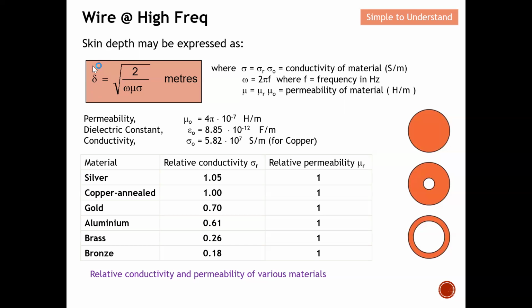Okay, because when I reduce the skin depth, I'm going to have a more severe issue. When my frequency increases, my skin depth becomes smaller, which means it will look like this condition. When my frequency is low, this thing is still bigger than earlier on, so I will have this form as a skin depth. So in short, you can see that the higher the frequency, I'm going to have this kind of situation rather than this. Okay, so this is a quick definition of skin depth.